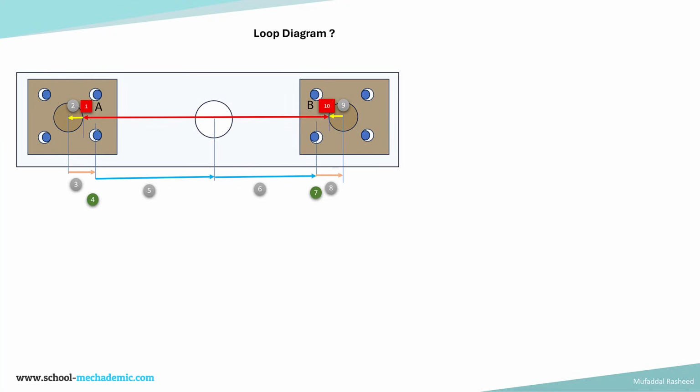That variation in angle of the post will cause an increase in the gap, which is accounted by specification number 1. So specification number 1 is the distance increase in the span between the 2 posts due to the variation in the angle of the post, which we had seen earlier, 90 plus or minus 0.5. So that's the first type of variation.